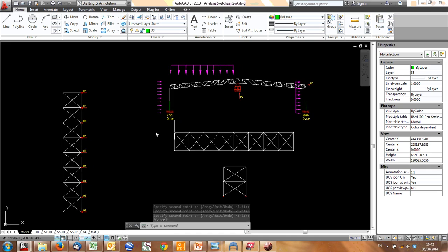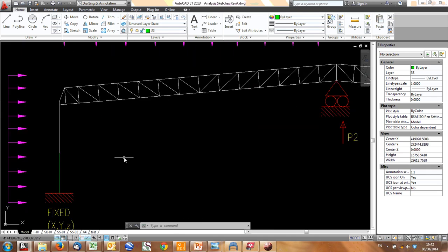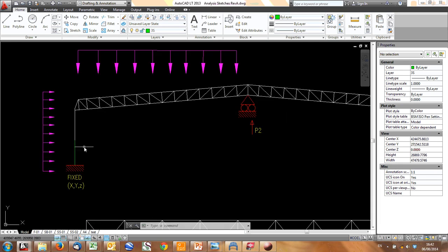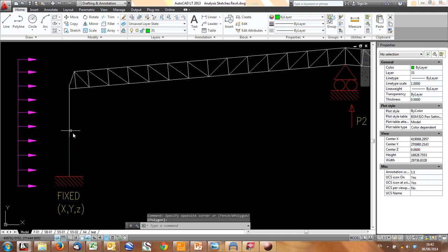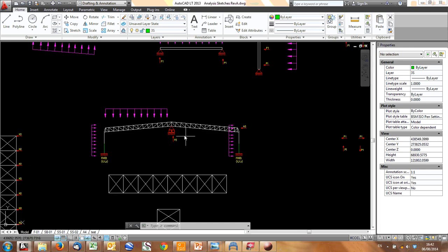But before we get that, think about that question when we come back and finish off this model. We've got this, but there's also a couple of other things missing. There's one missing. How are we considering this connection from the steel in white to the concrete in green? If it's a fixed connection, what's shown here is fine. If it's a pin connection, however, you have to be careful.